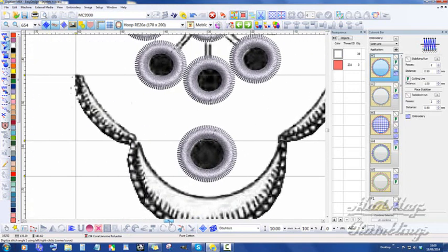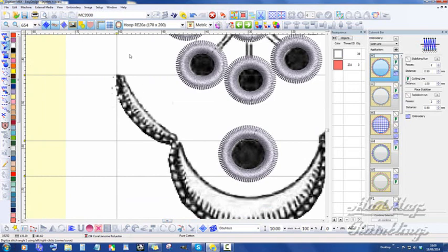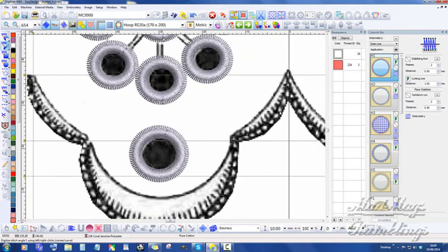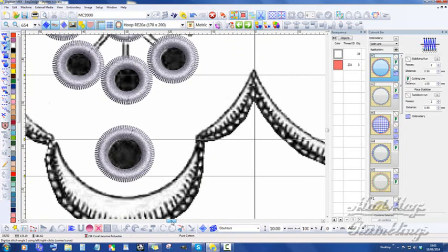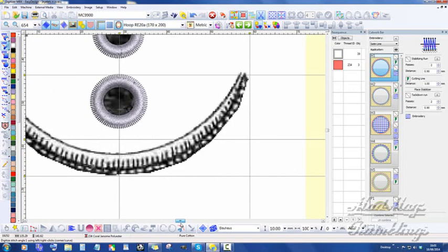And if I bring this one into 59 millimetres, that would make that one 29 millimetres. So that's where my actual join is going to be, just there. And I just want to touch this up a little. That's better. Am I being fussy? Yeah, because I want this to work.